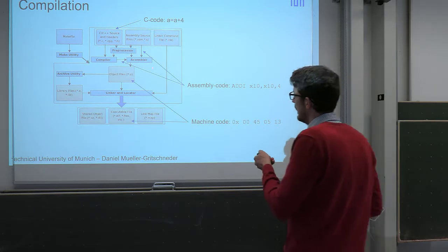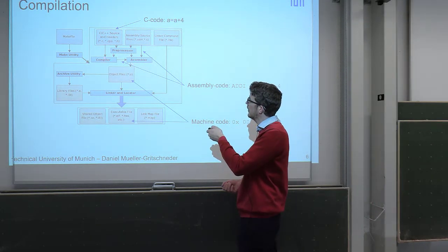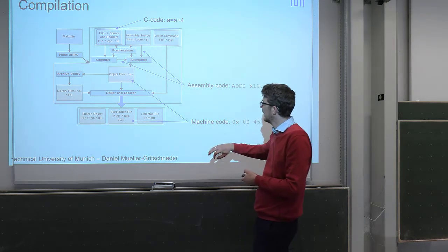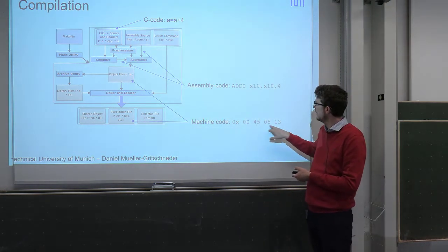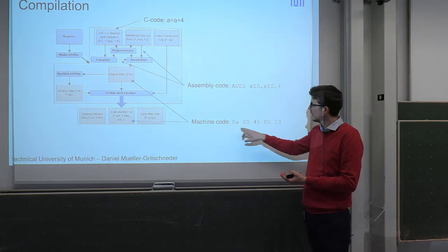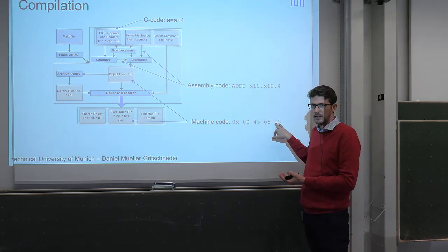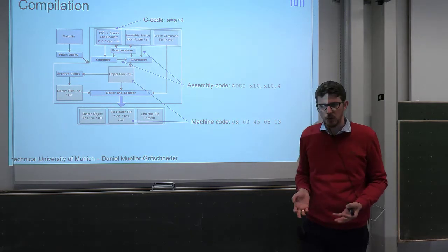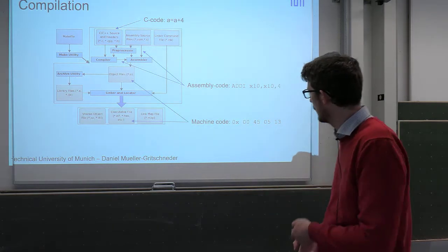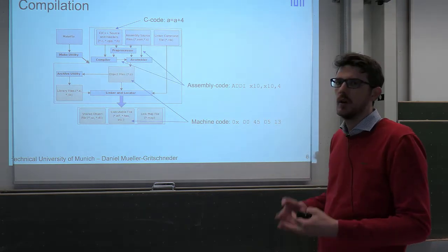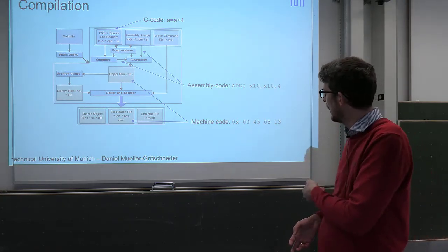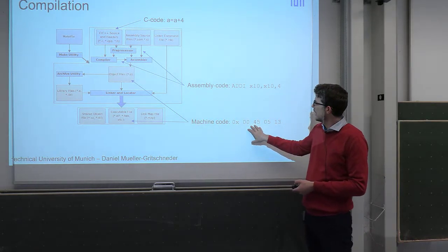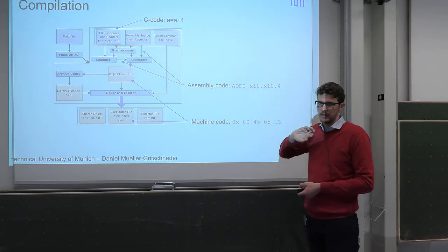And then the assembler takes this assembly code, either directly or from the compiler, and generates your machine code. The machine code would really be a hex word, a 32-bit binary value in this case, and this is the value you would find in your memory on your processor, which is loaded by the processor, and then the processor knows this binary value represents this instruction.